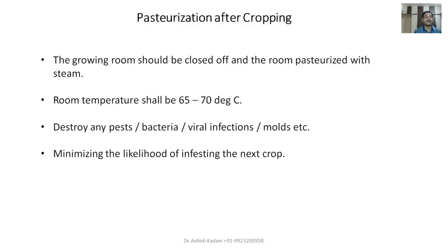So that is also another problem I have observed, that people are frequently opening the doors of the growing rooms, and they are disturbing the environment. So we have to ensure a uniform, undisturbed environment, and that is another reason people are promoting the technology. People are suggesting to go for a higher level of technology implementation in mushroom farming. So you can ensure the temperature of 65 to 70 degrees centigrade for the pasteurization through your centralized monitoring station, that is called the SCADA room.